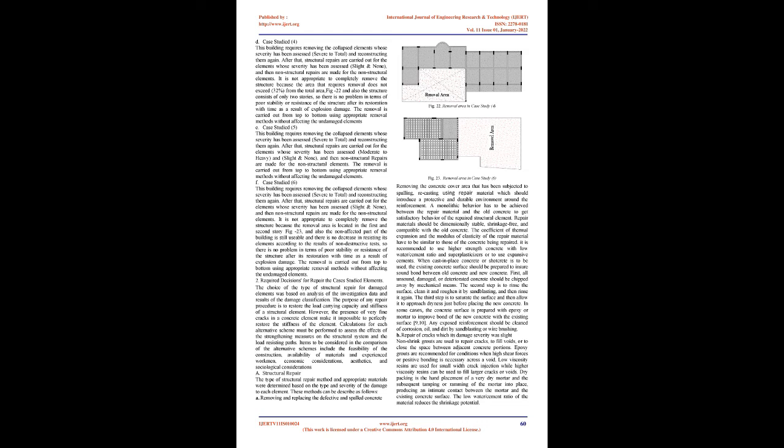It is not appropriate to completely remove the structure because the area that requires removal does not exceed 32% of the total area (Fig-22), and also the structure consists of only 2 stories, so there is no problem in terms of stability or resistance of the structure after its restoration with time as a result of explosion damage. The removal is carried out from top to bottom using appropriate removal methods without affecting the undamaged elements.